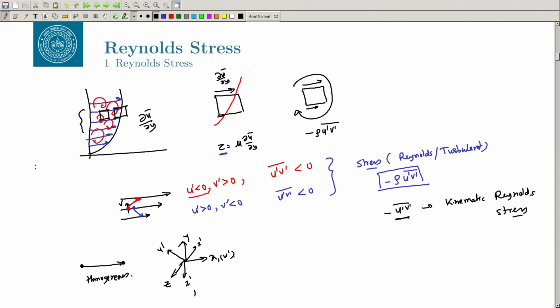Of course, it cannot happen if there is a wall there, because there is a motion on the walls, it will impart some directionality. So, it cannot remain isotropic, but for a general flow, let us say the turbulence in a box with all periodic boundary conditions, you can have an isotropic turbulence. In fact, this assumption helps us in our viscosity model, we will discuss that later, right.